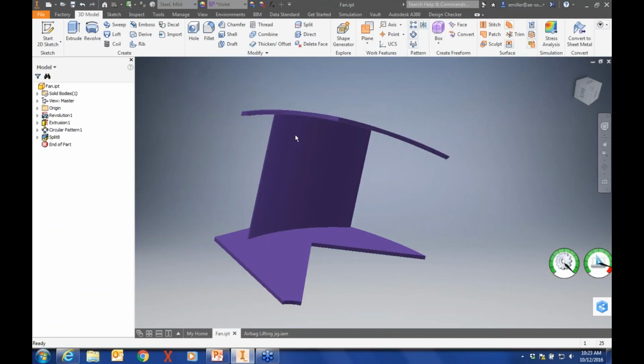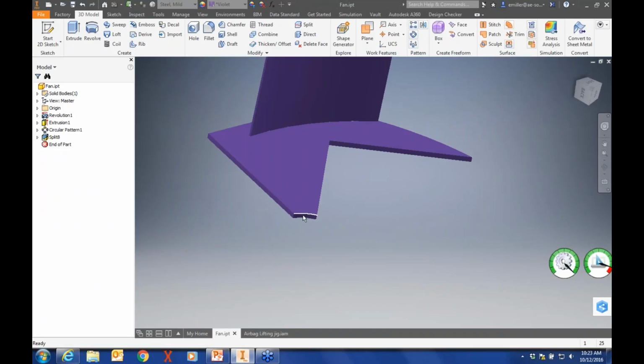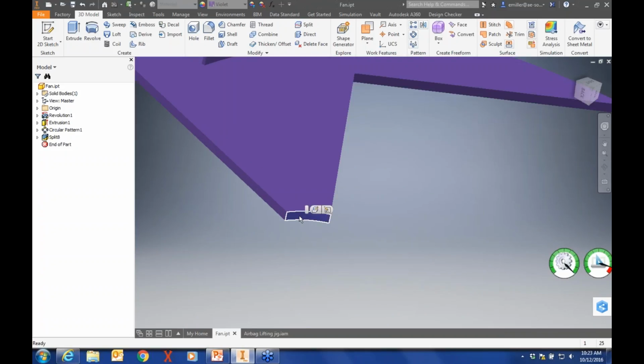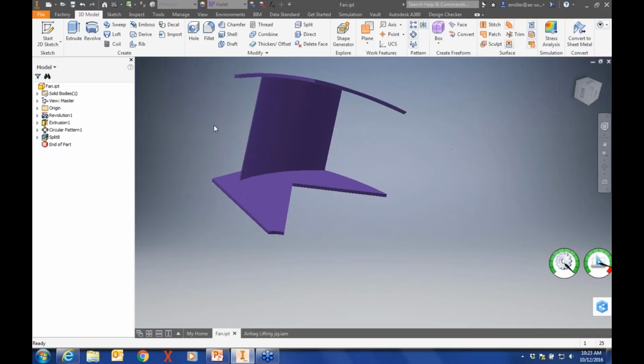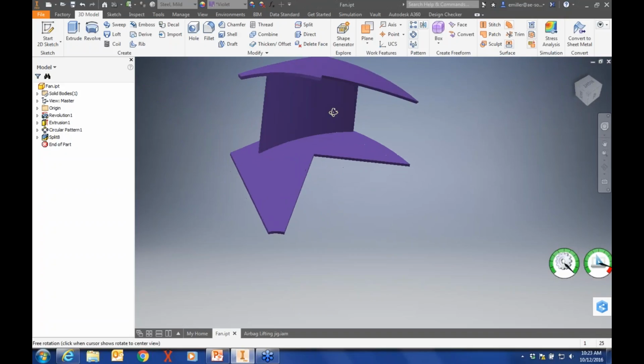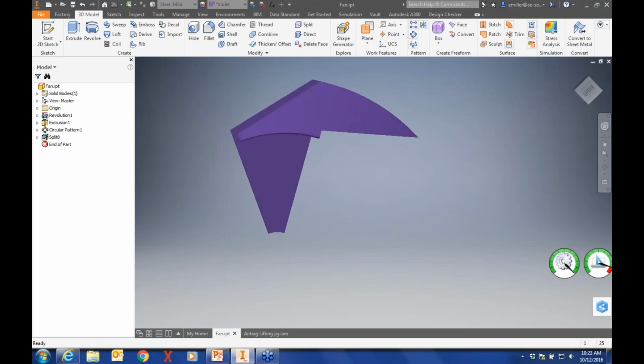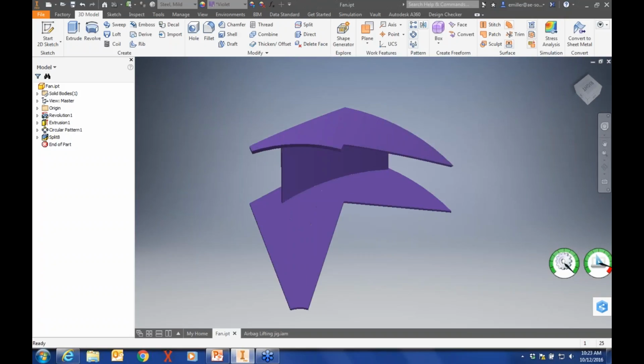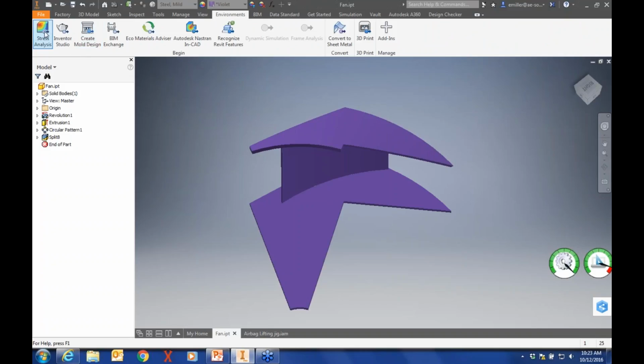Now, obviously, in this case, if you've got some type of drive shaft in the middle, maybe the force is going to be applied to this. So we put a rotational force in there, and then we could set up some of the other constraints on the other surfaces in order to complete an analysis there. But again, for the sake of time, let's jump back to the other one. So this was just an exercise in simplifying my model where there is some symmetry. Now basically we'd go into our simulation environment, start the stress analysis, create a study, add our constraints and loads, and that's the next phase of the analysis workflow.